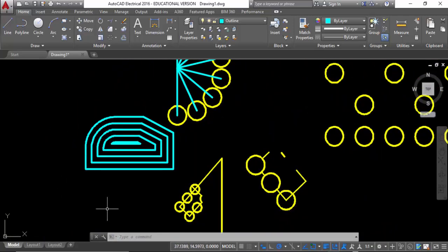Now there's offset that I would use for housing walls. If you are in South Africa, we would use our internal walls at 110 millimeters, or your external walls at 220 millimeters, or it can go up by 240, 250.